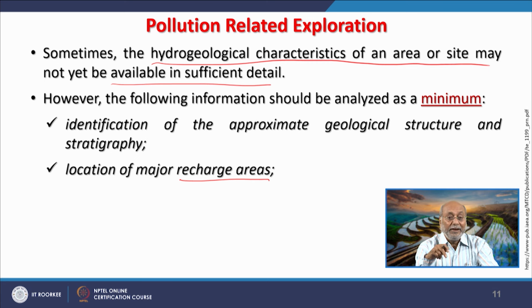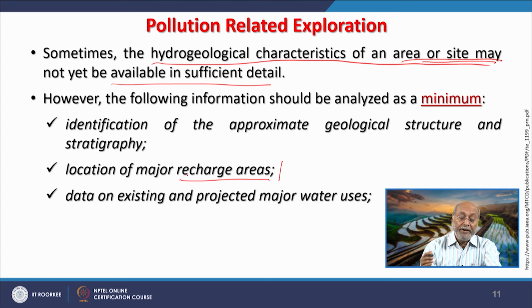These recharge areas will recharge your groundwater regime, and if a disposal site comes nearby, then the entire aquifer system, especially the confined aquifer system, will become polluted, and that is a big problem. So, these disposal sites should not be anywhere close to the recharge area. That kind of extensive hydrogeological information is required.